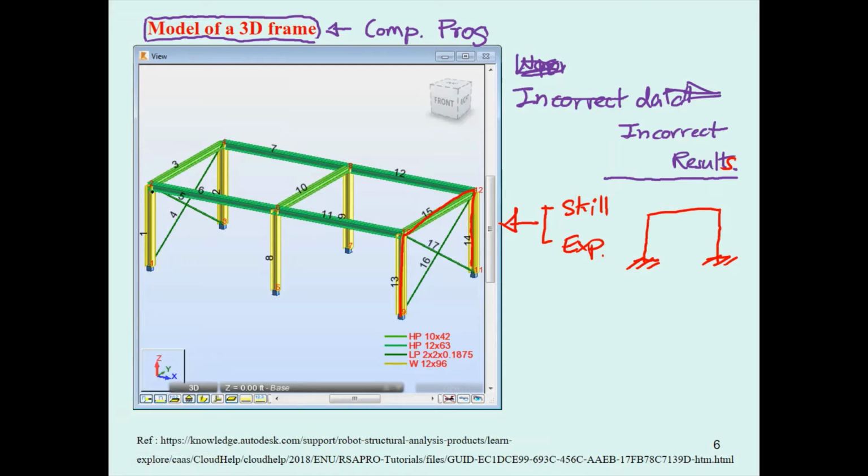But if you model this structure in this direction, your frame is going to be more complicated. Now, your frame can be modeled in three dimensions like this. And again, if you check for the degree of indeterminacy, this one will have 9 unknowns, 3, 3, 3. Then you have only 3 equations from one free body diagram. So this one is going to have 6 degrees of indeterminacy. It's going to be a tough job if you do the manual calculation.